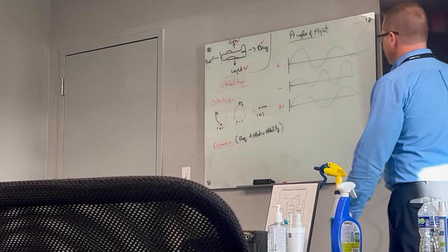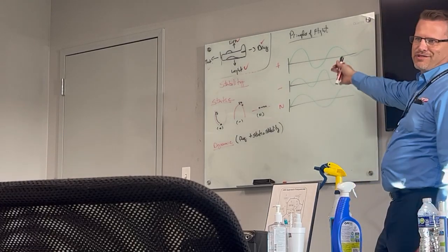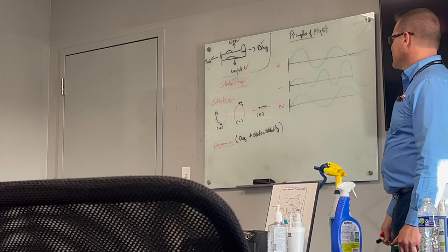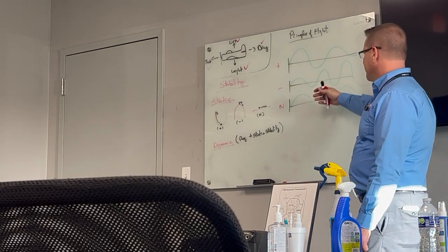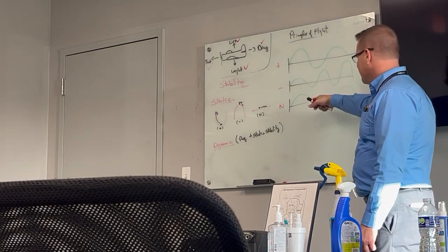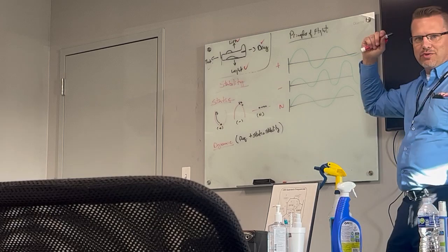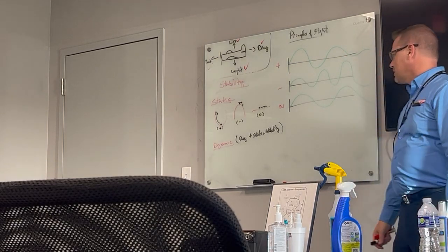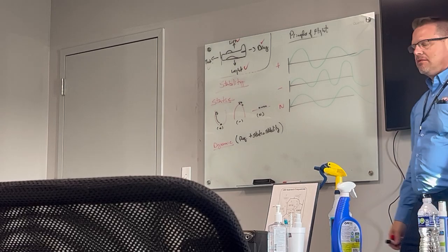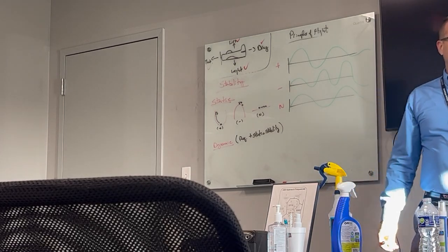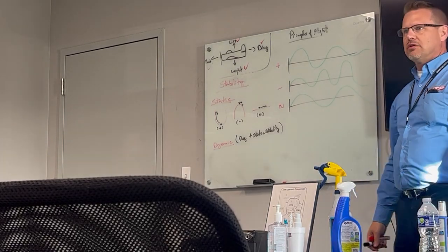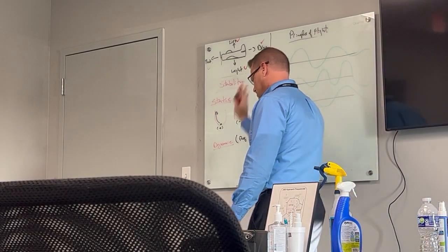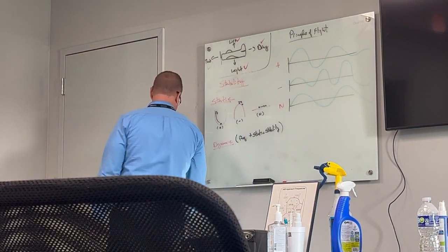And then, so obviously this is over time. These are the graphs. Positive: if there's a disturbance, it gets less and less over time until it returns to equilibrium. Negative dynamic stability is it tries to return, but it never can. It gets worse and worse with each attempt. And then neutral is basically a perfect sine wave where it starts and it just never ends, right? It never gets closer, never gets further away. It just continues that equal oscillation on both sides of the equilibrium.